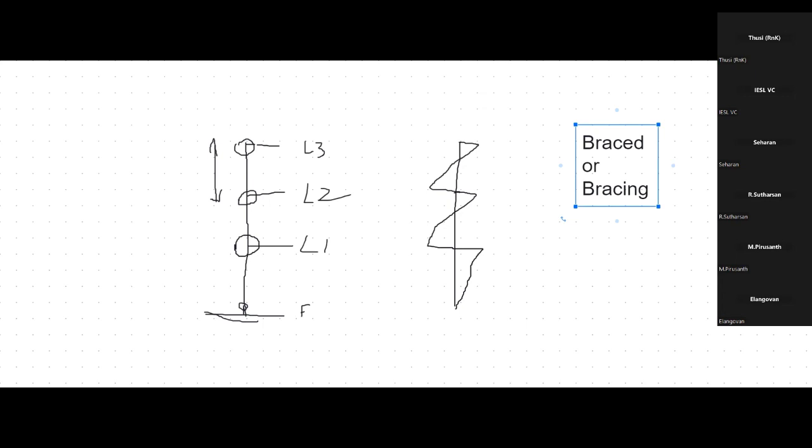So now the software is asking whether you want to include this structural depth or not, the beam depth or slab depth, right? Generally, I choose this one. That means the effective length of the buckling is considered only this one. But some design codes allow taking only center to center. Some design codes have a reduction, but Eurocode allows going until here. So I am going to use this method.